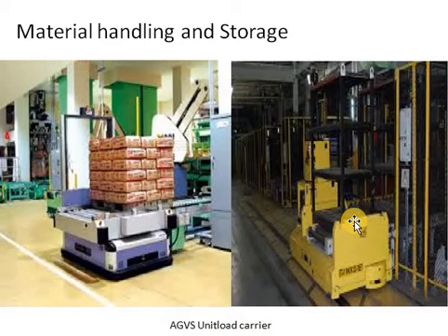a material handling system which uses independently operated, you can say self-propelled, vehicles that are guided along defined pathways in the floor. You can see here, the vehicles are powered by on-board batteries. Guidance is achieved by a sensor on the vehicle that can follow a guide wire.